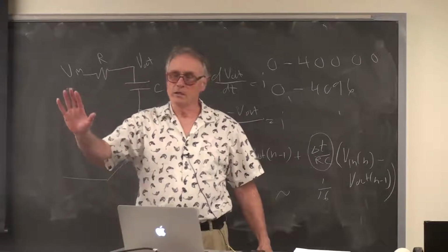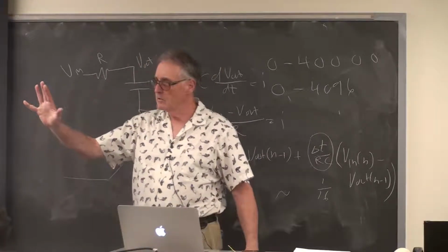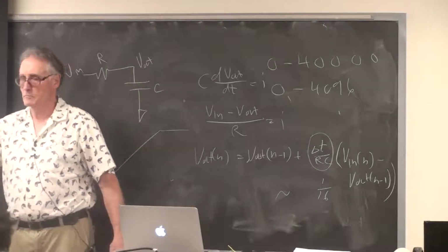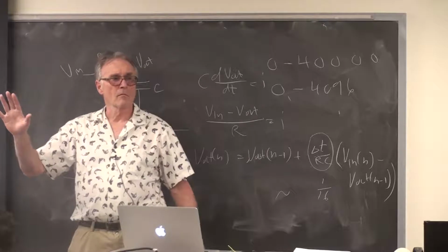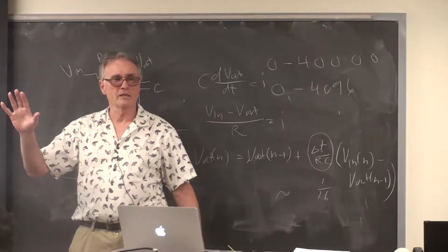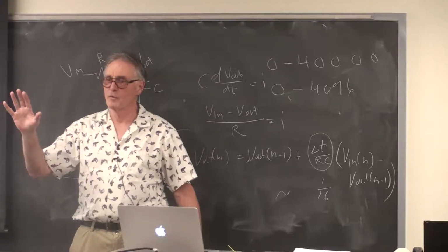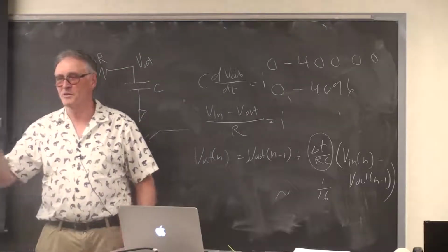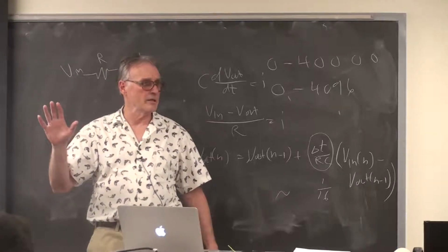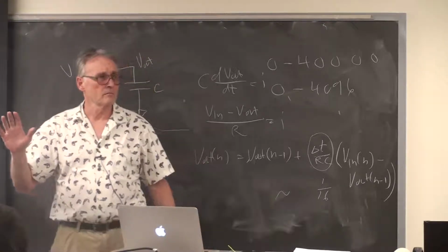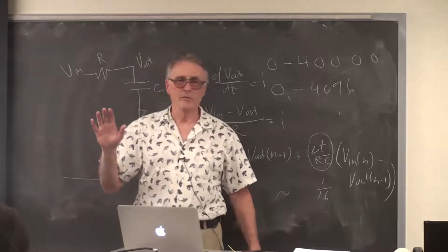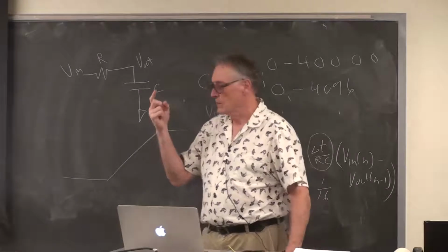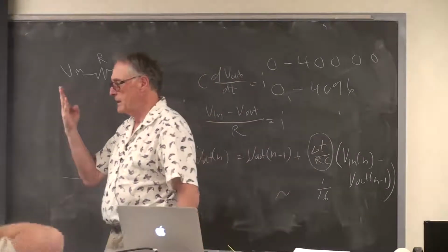The only logic that's going to be outside of the interrupt service routine is the user interface. I suggested using a simplified user interface consisting of 1 trim pot and 2 buttons. But if you want, you can do the keypad instead. You have to be able to input 4 parameters: desired angle, KP, KI, KD.